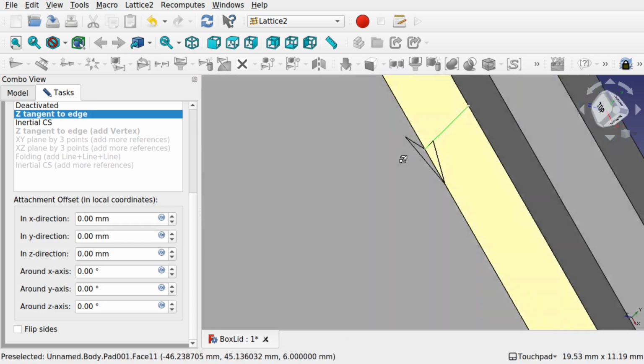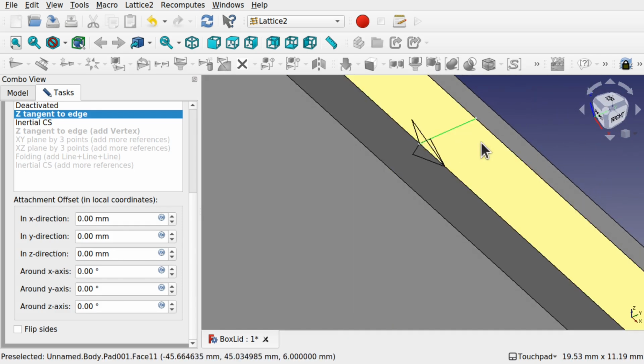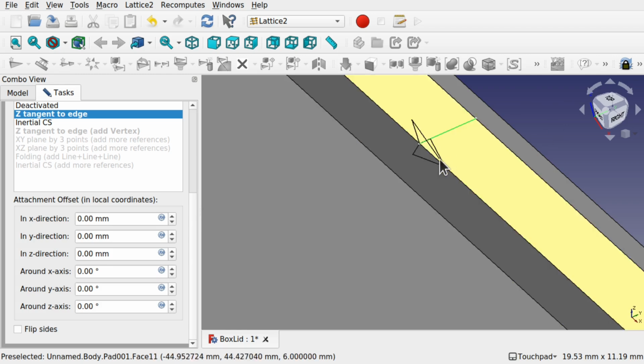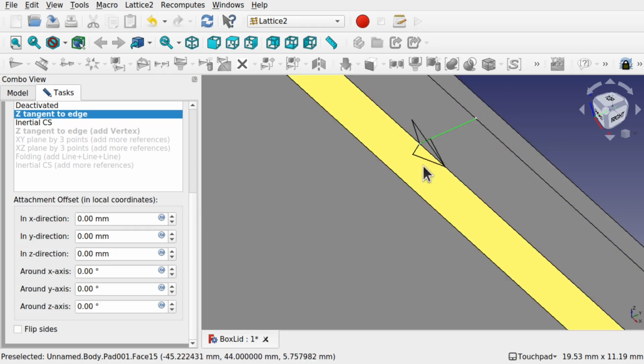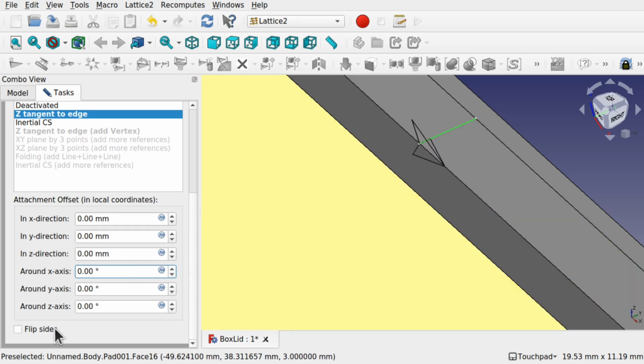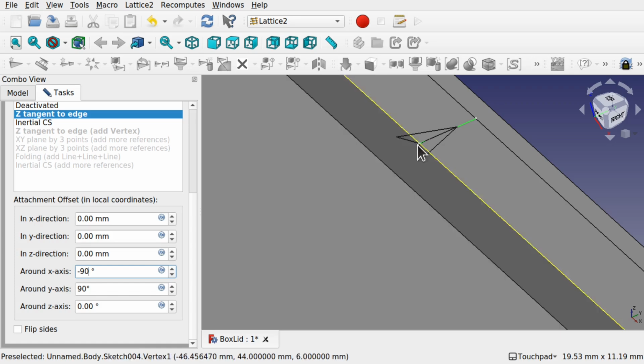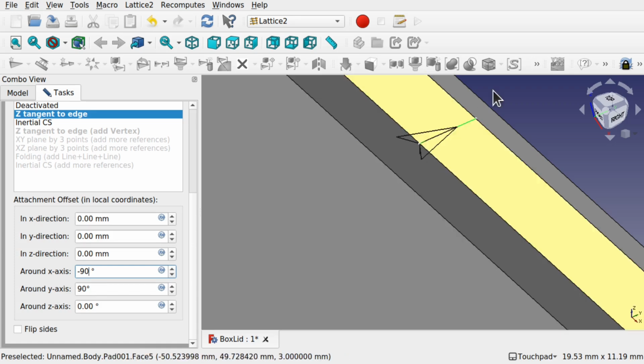So we can see how that kite's been placed. Remember how we wanted the latch to be placed, and we want the latch to be facing this way with the ridge that's been removed this way. So we've got to place this in the correct position. We can come back and change this if we want, if we get it wrong. But that's rotate around the Y. So 90 degrees. And then rotate around the X. That's minus 90 degrees. So we've got that kite there. Our latch will be placed at the point of origin there in this orientation or rotation.